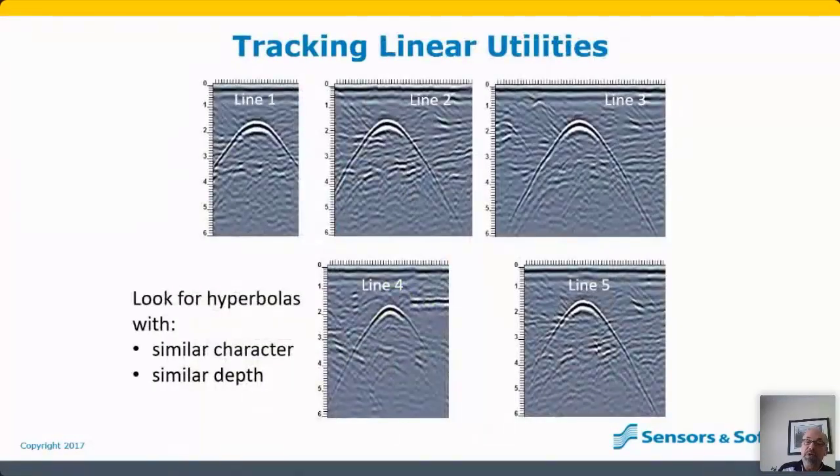And each time you collect a line that crosses the utility, you hope to see something like this. Hyperbolas with a consistent depth and similar character. This is what gives you the confidence that you are following the same target and having success.